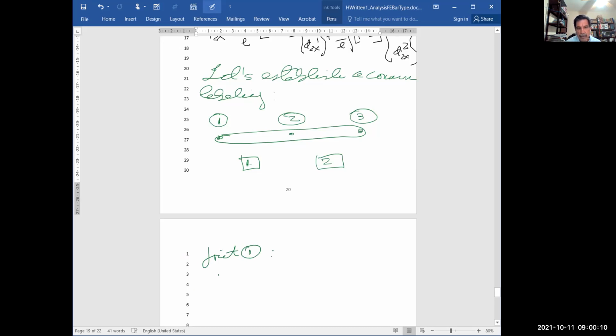we call it F1x, and it's going to be equal to EA over L of the first element, and then we go 1, minus 1. And here, since this is the first element, and this is joint 1, we simply say this is D1x. The other one is going to be D2x.